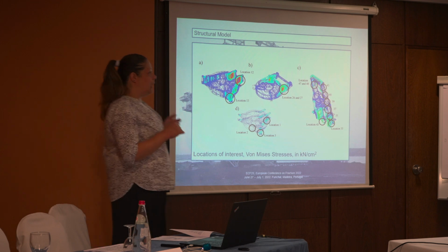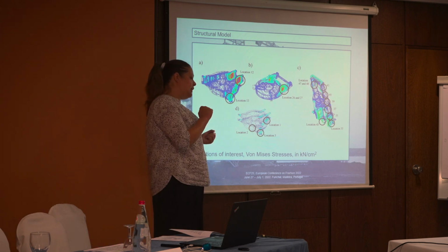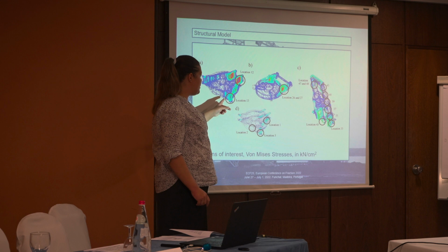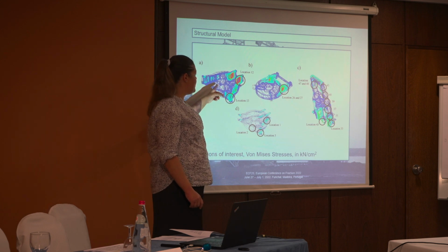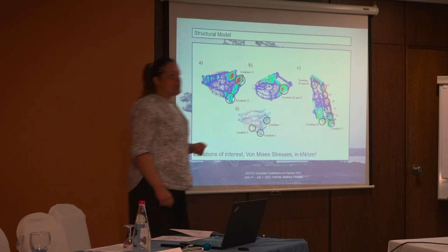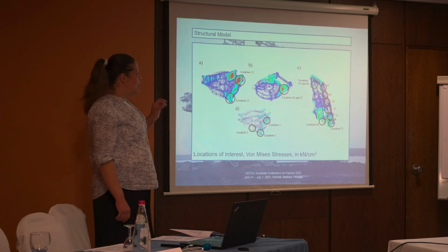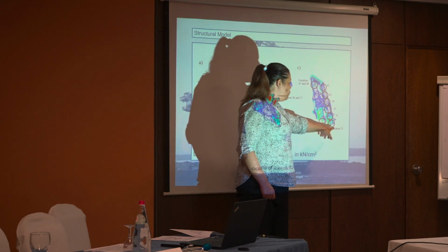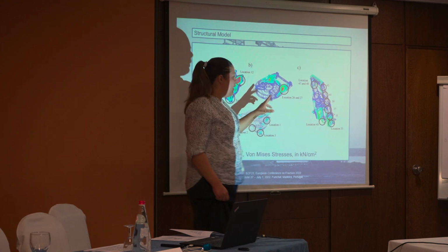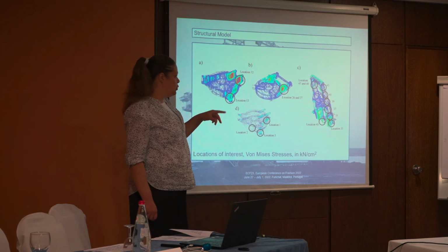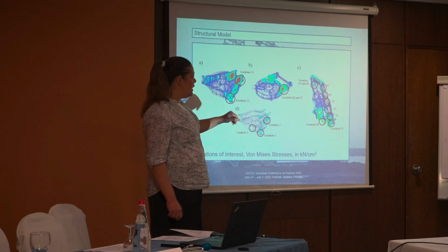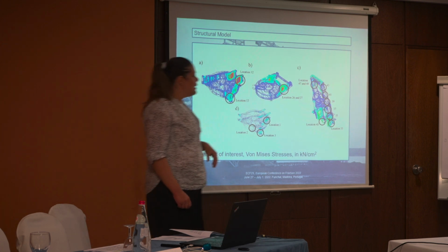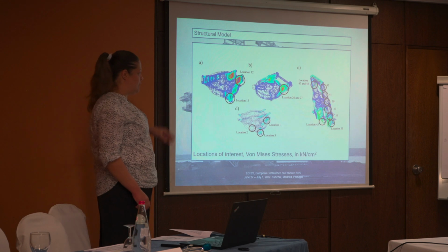So we got, I think, 5 spots in every plate that included zones of stress concentrations, zones of the back supports, and some in the zone without a high stress level. And that was the philosophy of mapping the model. So pylons were divided into 6 zones. In each zone we got two spots, right pylon, left pylon, and some zones of stress concentrations in the truss that connects the pylons. We also got stresses.